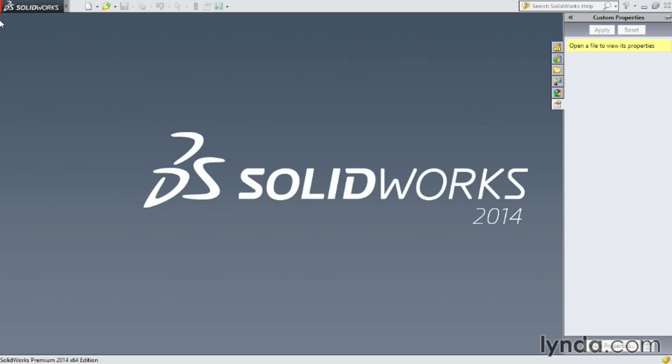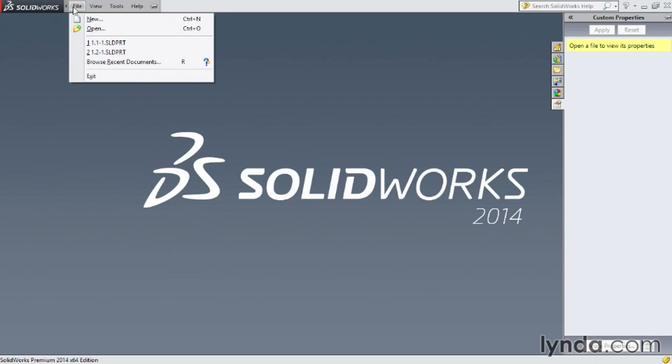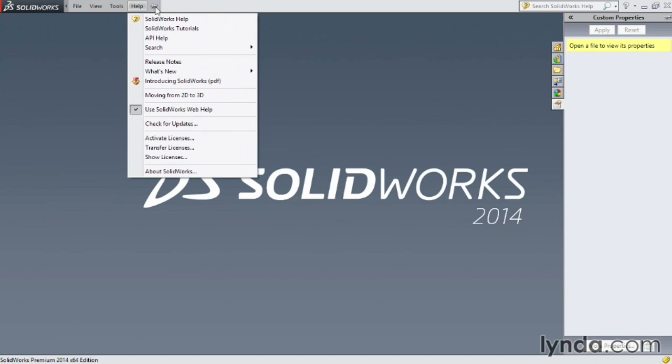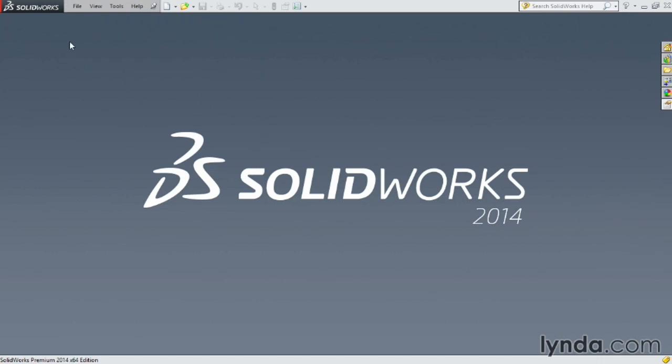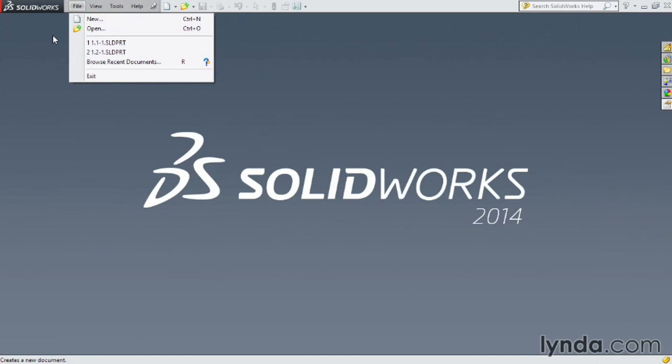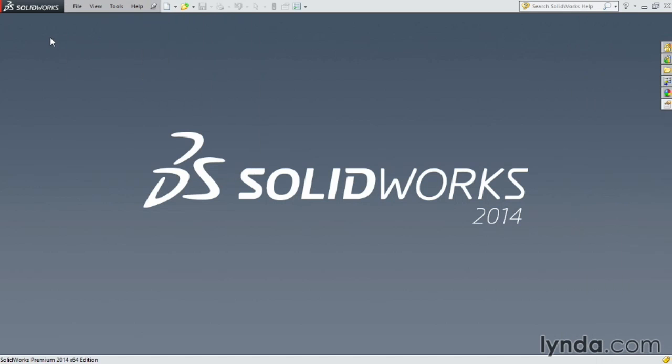To get started, first I'm going to come up here to the SolidWorks logo, and directly next to that is a little arrow. If I click on that arrow, notice there's a little file menu that pops up, and if I go to the very end of that, if I click on the push pin, that will stay out. I like to sometimes get into these file menus and actually open files from there, so it makes it really easy. To get started, the easiest way is actually to click on this blank sheet of paper called New.